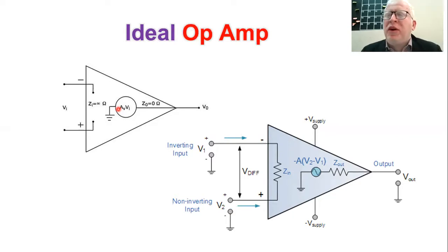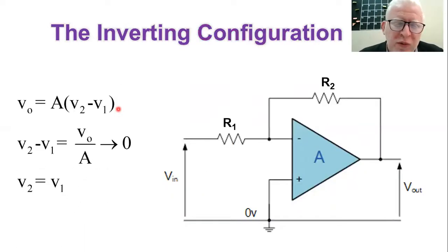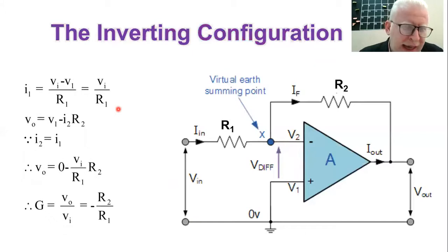So you go to the market, you buy an operational amplifier, its gain, for example, is 50K, then it's a constant. However, whenever you have a closed loop configuration, we concluded that the gain, which is V2 over V1, is equal to minus R2 over R1. So the first important feature of this gain is that it is controllable. I mean, you can control the value of the gain by controlling the values of R2 and R1, which are discrete separate resistances.